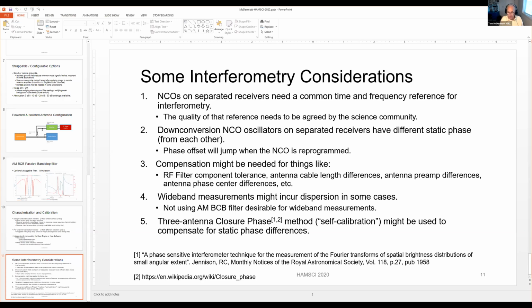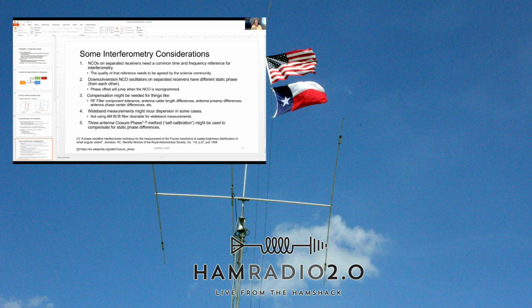I think there are other temperature limitations in the entire package related to capacitors. There are electrolytic capacitors all over the data engine and RF receivers, and I think those will have their own temperature limitations of around 0 to -20°C. So in extremely cold locations, it may be required to put the data engine and RF receiver module in a heated enclosure.